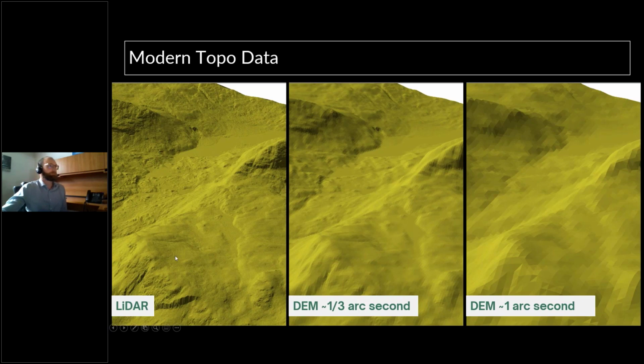So from a planning perspective, obviously, LiDAR is my preference. But even if I'm just trying to figure out where stuff's going to go before I decide to purchase either conventional or LiDAR survey data, I could do my plan with these other data types to at least get a rough idea of what my options are.